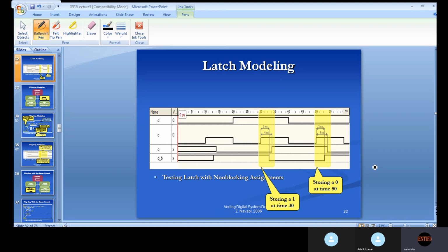Also, sometimes error values can come, like when swapping the values of 2 variables. When there are A, B, C, and C depends on B, which depends on A, C can't wait for a long time. The time delay will be too long in blocking assignments, and during this waiting time error values are taken and wrong outputs keep coming. That's why we go for non-blocking assignments.